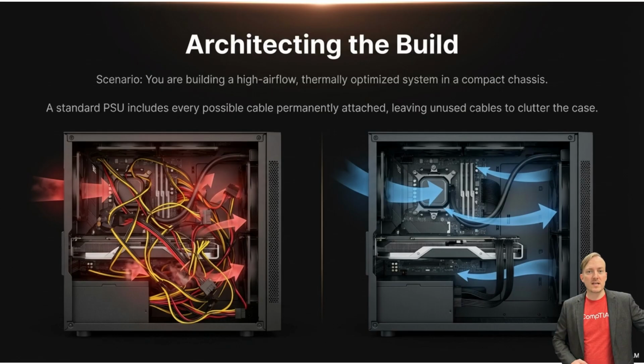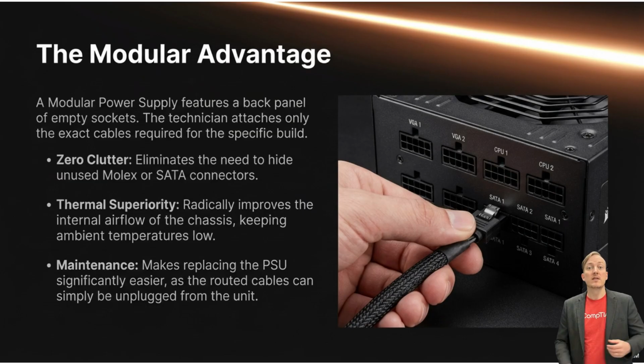When architecting the build, cable management matters. Scenario: you are building a high airflow, thermally optimized system in a compact chassis. A standard power supply has every possible cable permanently attached. If you don't use them all, you are left with a massive nest of unused cables cluttering the case and choking your airflow. To solve this, we use the modular advantage.